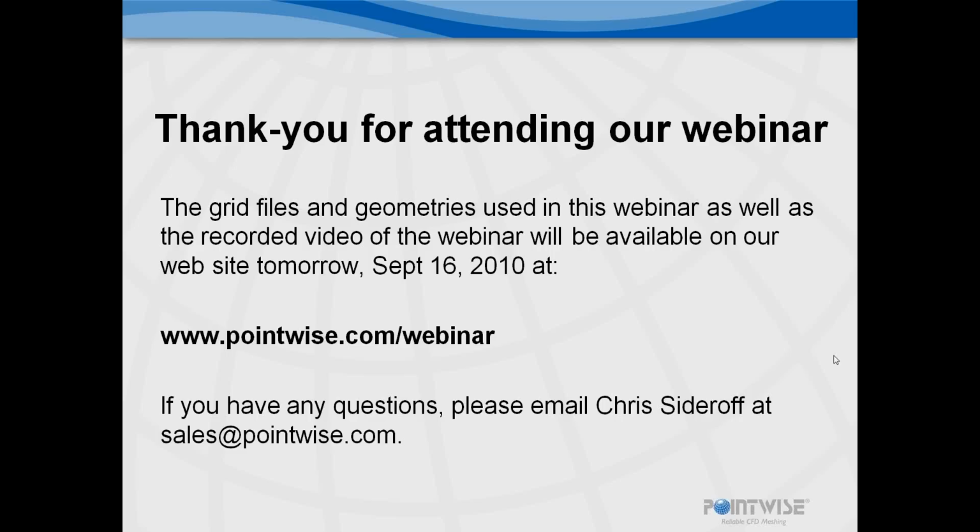And the thing here is that you just need to be careful with the approximations that are done in the way that your mesh is draped over the imperfect CAD geometry. Essentially what our surface meshes do in that case is they locally are projected onto the CAD surface, and if you need to have a grid resolution on the order of those imperfections in the CAD model, you may need to take additional steps in the projection stage.